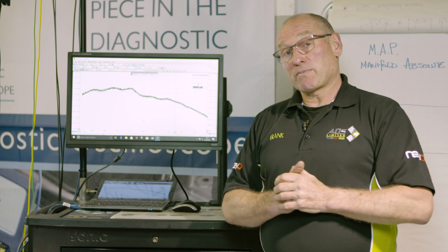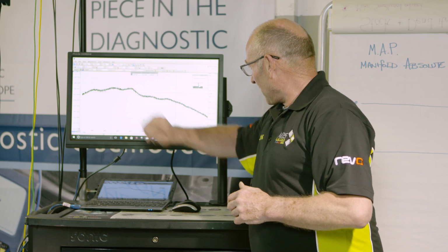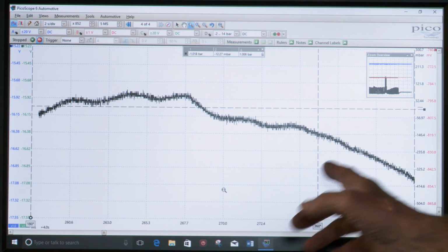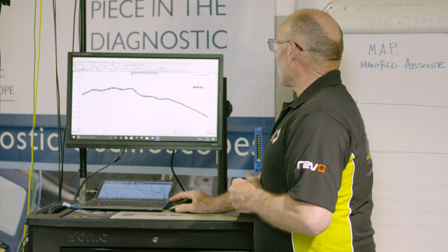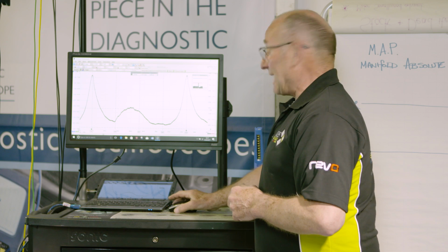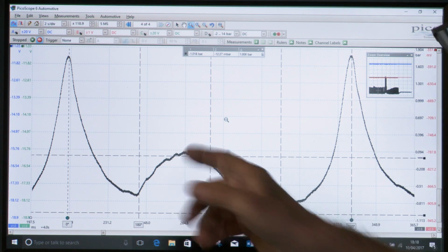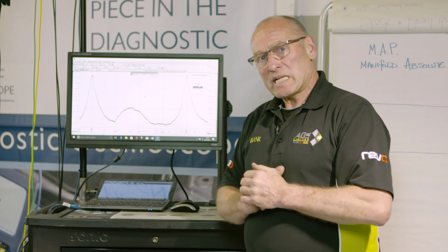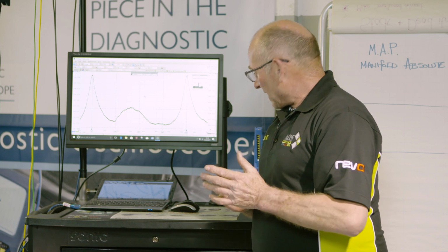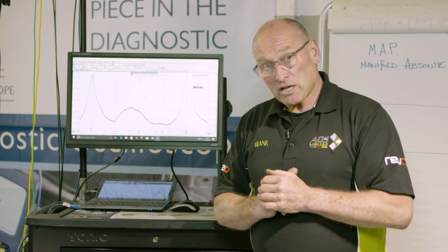You have a lower pressure in the intake manifold, so the inlet valve must have opened at that point there to create this change, because there's TDC. Piston's not yet at the top. So we now know where the intake valve has opened. Why have they opened it so early? There's a very interesting reason for this, and that is that this engine and some of its family members do not use an EGR valve, thank God.